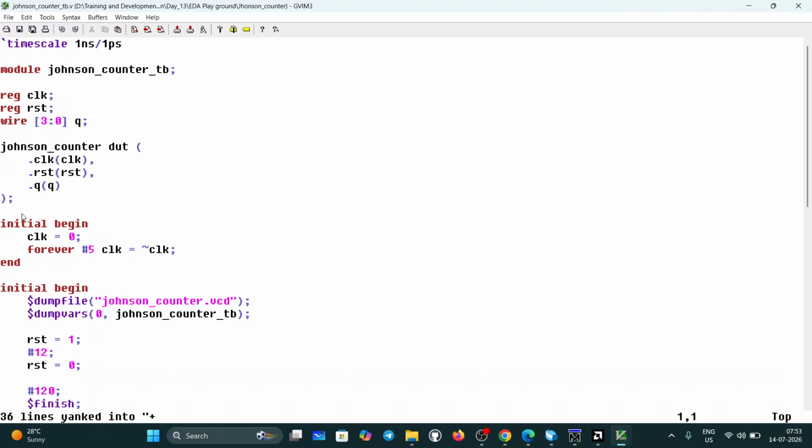The test bench for all the sequential circuits is the same, and for all the combinational circuits is the same. For the combinational circuit there are four steps: initializing the edge variables, initializing the variables of the test bench, instantiation, and giving the stimulus. For sequential circuits, one more step is added, which is generation of clock.